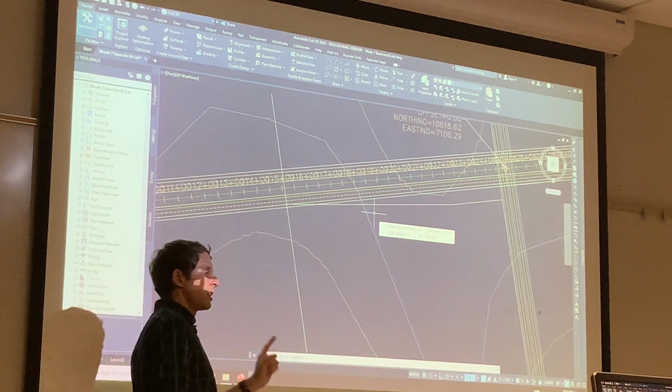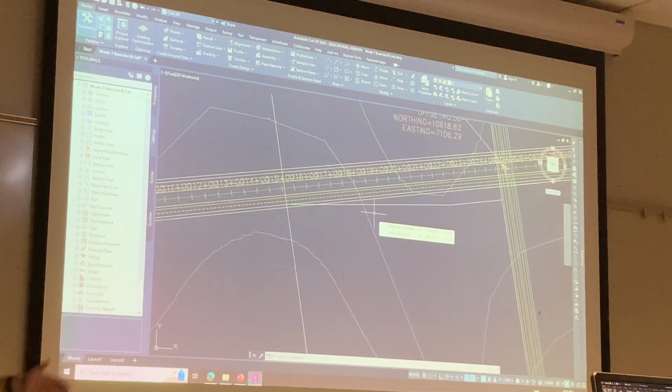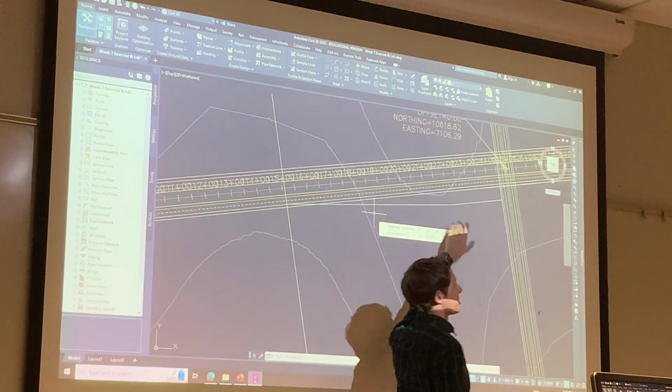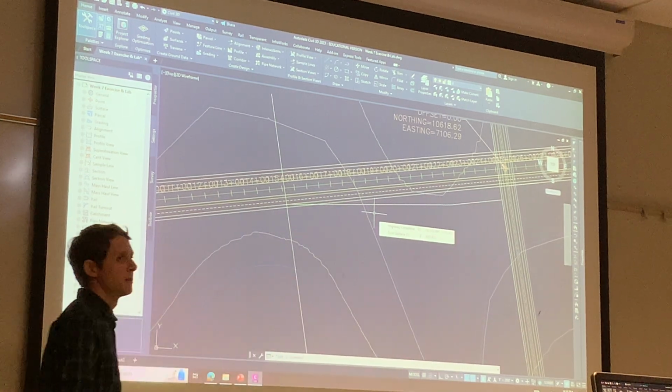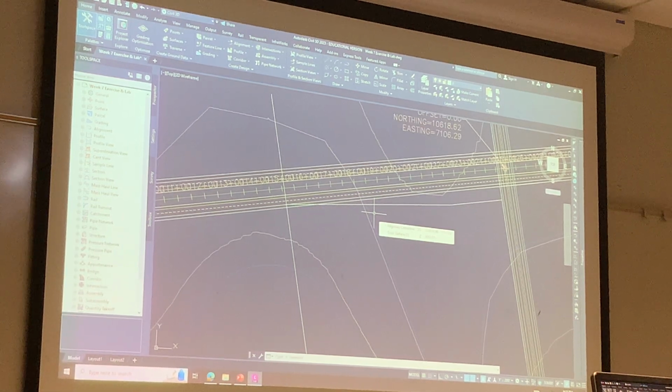Now, the one thing that I want to do before offsetting this line to create the plan, the layout, is figure out what radius this needs to be. So guess what I do? I figure out what the design speed is going to be. Do I need to match it to the existing highway's design speed, or can I interpolate between 50 and 25, or between 65 and 25? Well, we would do the math.